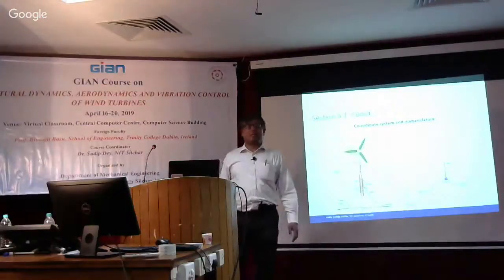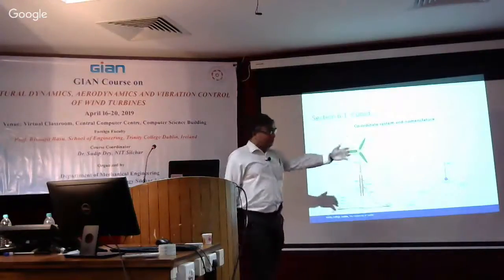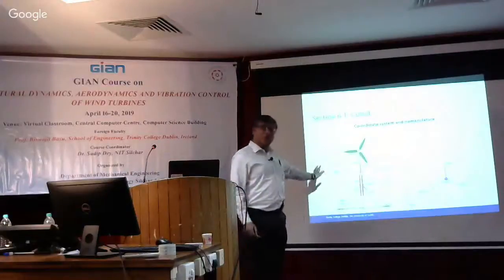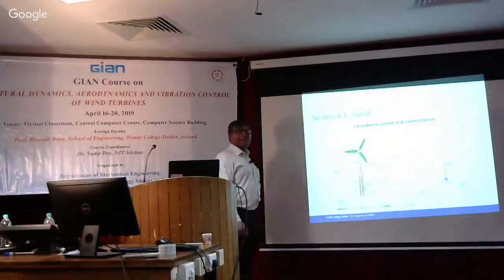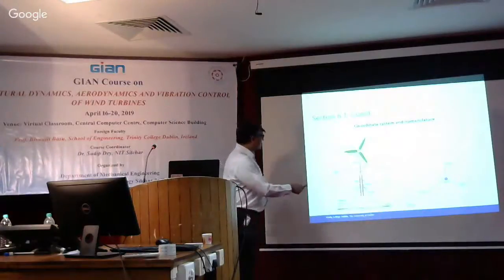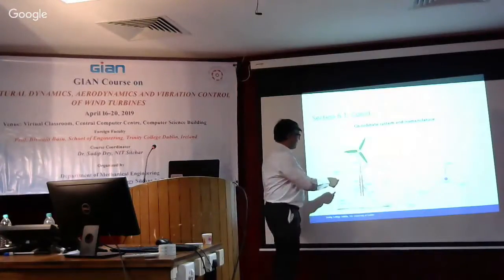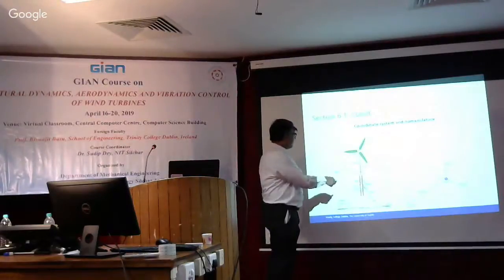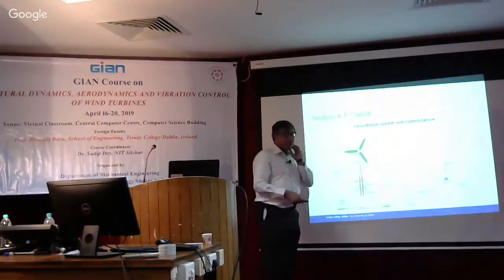And there are two ways to model that: either you couple it with your potential theory, the Laplace equation, or take the full Euler equation, and then you will need boundary conditions actually. Because then what is the boundary condition on this place? You can assume this part will be implicit, and then there'll be some pressure boundary condition here. Maybe some viscosity is also there. So you'll have a normal boundary condition and a tangential condition as well.